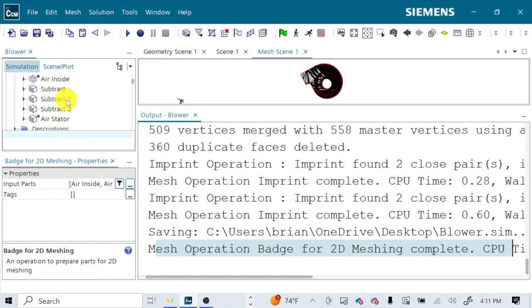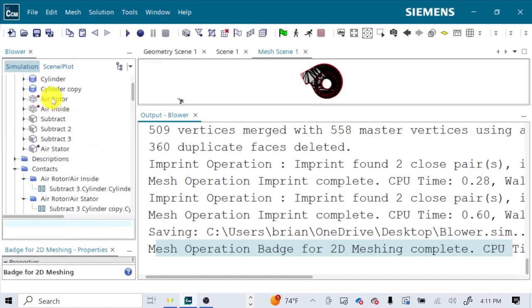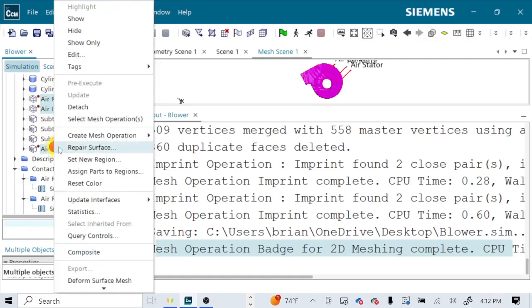And if we look up here, this is one way to verify if it worked or not. Do you see a little red dot next to the things you tried to make 2D? If you do, then it worked. If you don't, then it didn't. Usually the reason it didn't is if you don't have an appropriate plane or a surface on the appropriate plane is the usual reason for it to break. But it did indeed create our 2D domain based on this, so we can select all three of these and turn them into regions.